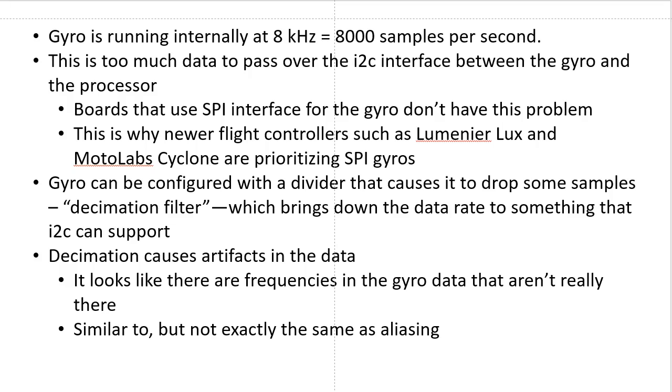Let's get into it. So the gyro is the sensor on the flight control board that feeds inertial data into the PID loop. The gyro tells the PID loop the copter is pitching forward, pitching back, rolling left, rolling right, yawing left, yawing right. And the PID loop then takes that data and decides what to tell the motors to do to affect a desired change in that data, right? And so that's basically how the copter flies. The gyro feeds inertial data to the PID loop. The PID loop processes that data and outputs instructions to the motors, okay?